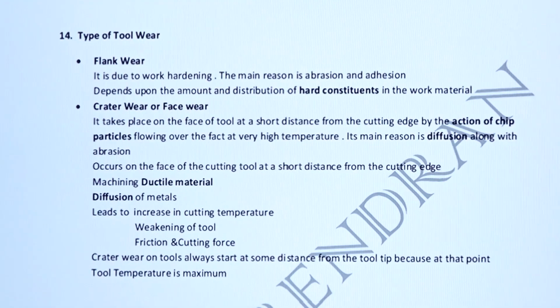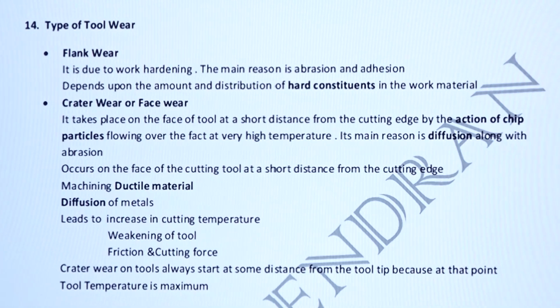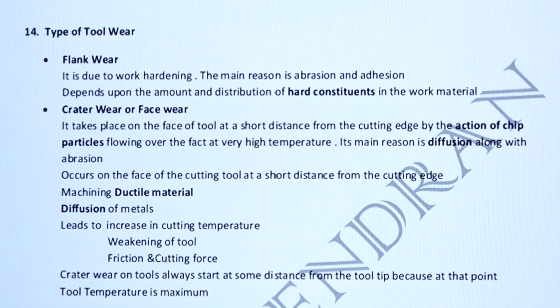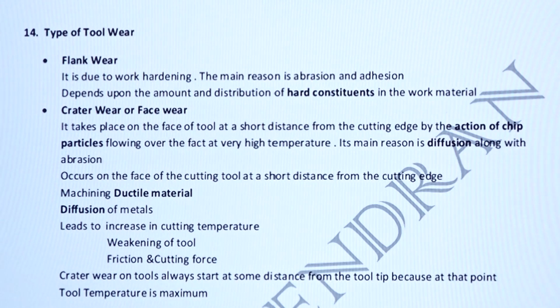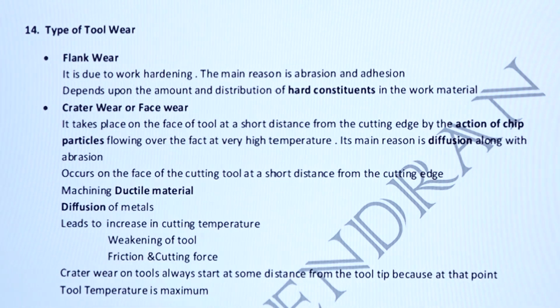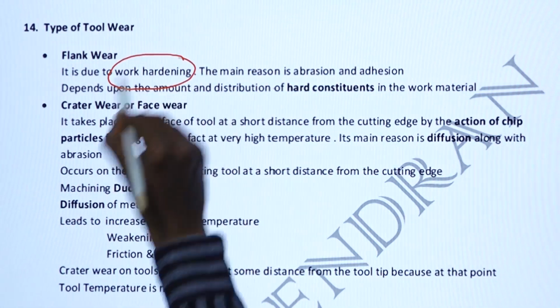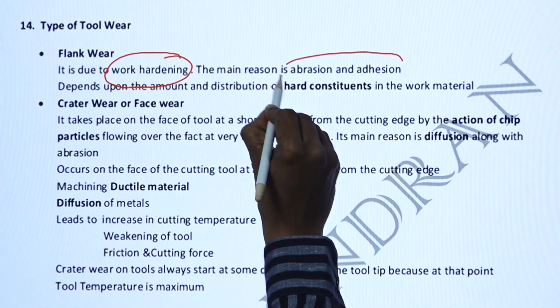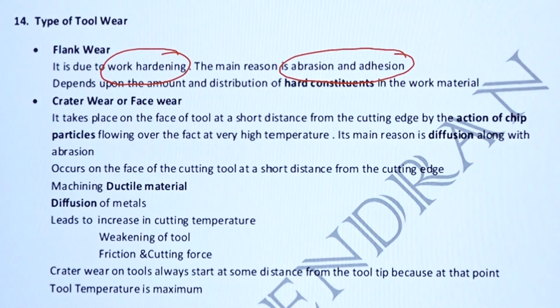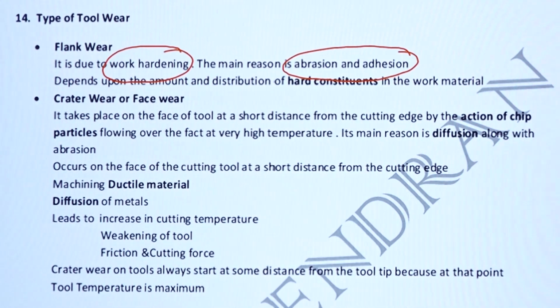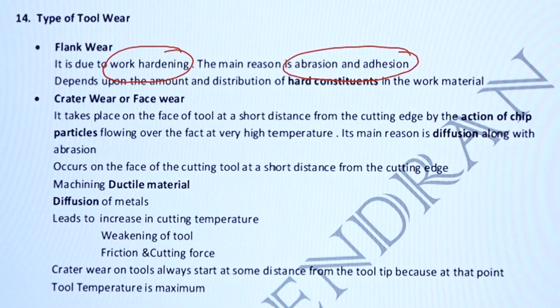Next, we are having types of wear. Types of wear are flank wear and crater wear. Flank wear occurs due to the work hardening, and the main reasons are abrasion and adhesion. The crater wear is also called face wear.